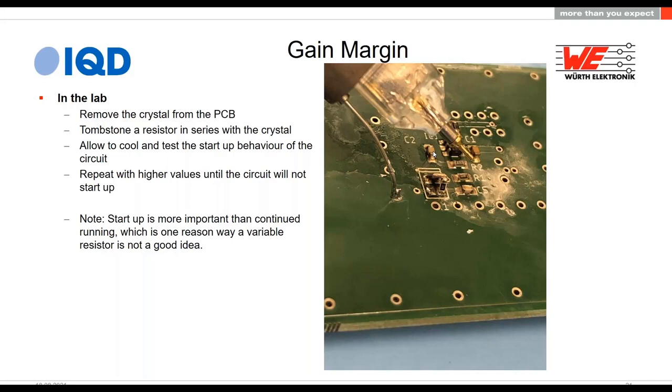I don't think that's very safe, because at the point when you very first start a crystal oscillator circuit, what's happening is that the amplifier begins by amplifying white noise, Johnson noise, thermal noise that's in the system, and then the crystal acts as a filter, blocks all of those frequencies apart from its resonant frequency. Yeah, so that's a really sensitive moment when that oscillation is getting going. It's the hardest part for a crystal circuit to work. Yeah, so by always looking at the startup, you're always looking at the worst case, the most flaky part of the measurement.